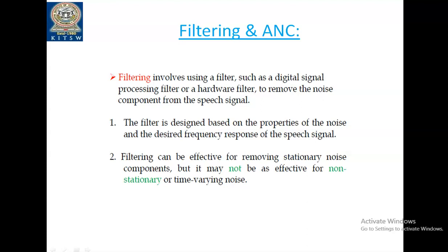The reason is that we need to apply the signal in the frequency domain in order to get the frequency response of the spectrum. First we need to apply the DFT or FFT, and this DFT or FFT is well suited for stationary signals. That is the reason, before we process further, instead of taking the entire duration of the recorded speech, we divide it into frames of 10 to 20 milliseconds, because during that portion we consider it a stationary signal, so that comfortably we can apply the discrete Fourier transform or the fast Fourier transform method.